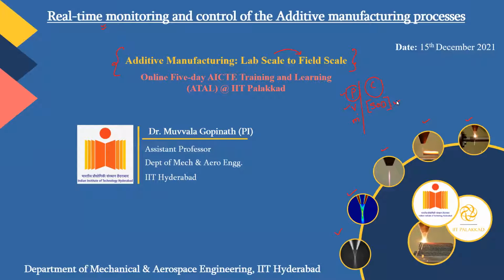So it is very vital to understand the effects of individual process parameters, and then, depending upon the problem you are facing, you do the real-time monitoring and control that particular parameter only, without touching everything else. Additive manufacturing typically has a large number of process parameters, not only from the laser perspective, like the spot diameter, the Rayleigh range, the velocity, mass flow rate, carrier gas flow rate, powder particle size distribution, the way it is getting focused, and the velocity of a powder particle. If you keep on counting, the number of parameters crosses 30 or 40.